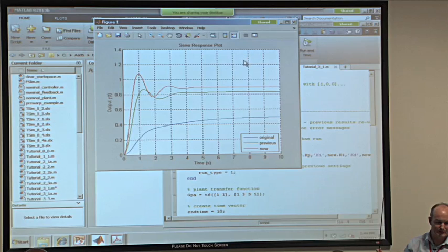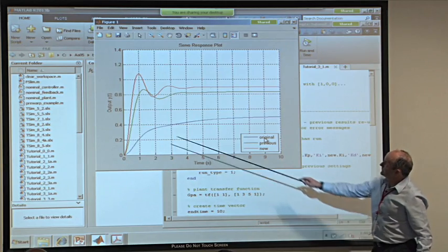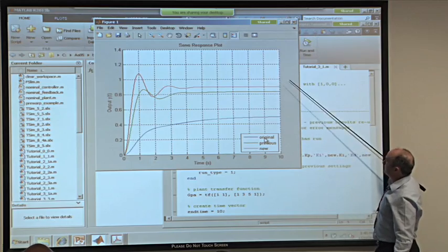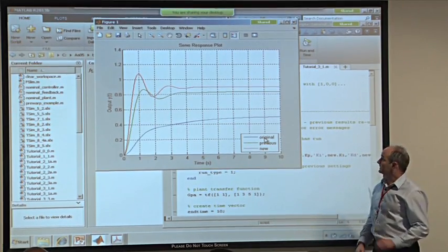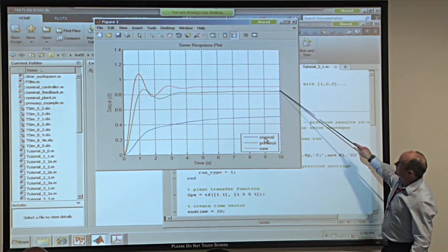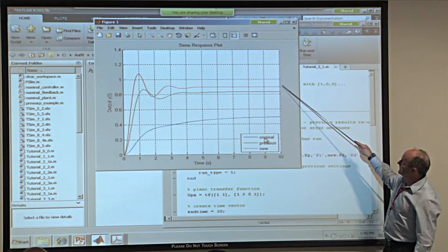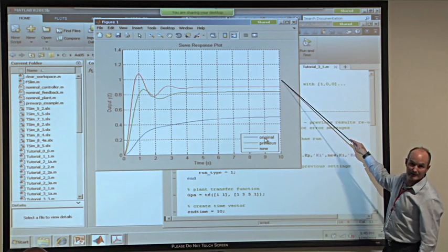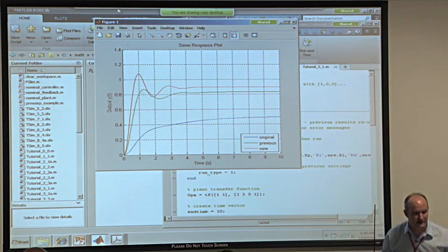If anybody strongly feels that we want to do something different, then let me know. And I would suggest that we're now getting towards the point where the overshoot is starting to be maybe a bit worrying, and we still haven't achieved 0 steady state error. And we're not going to, because you see we're into the region of diminishing returns here. There we went from a gain of 5, I think, to a gain of 10. It didn't make much difference. If we went to a gain of 1,000, we probably still wouldn't get to 0. We need integral gain to get rid of that steady state error.